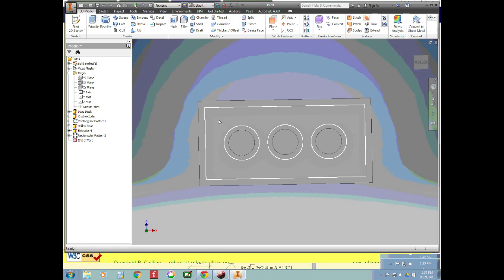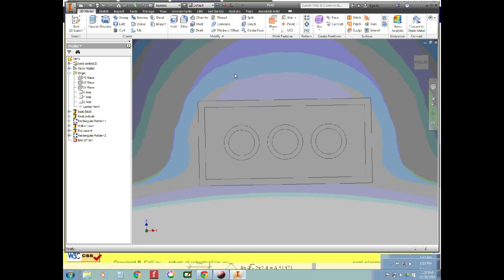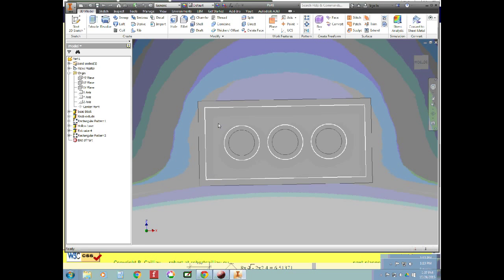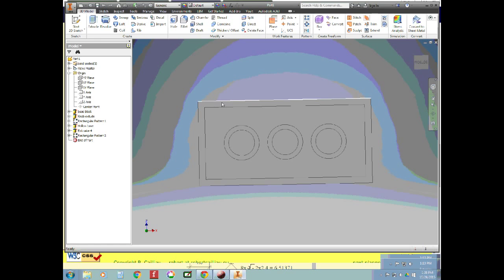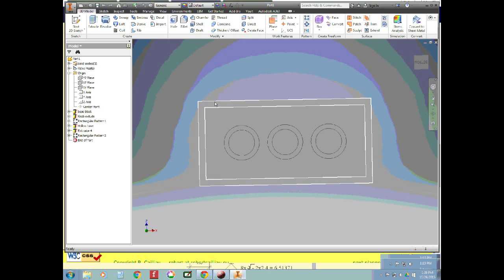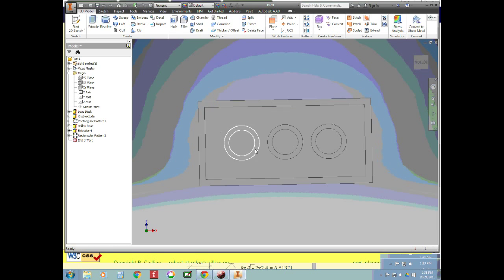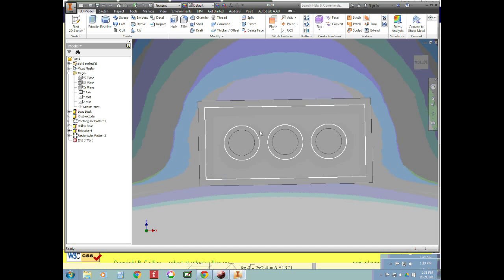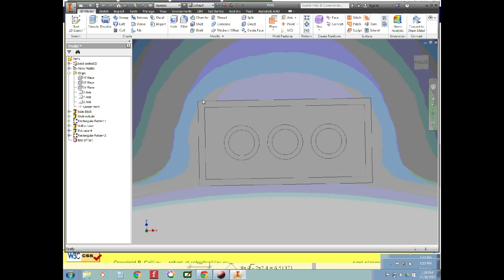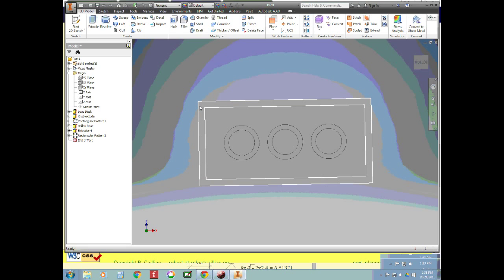We could draw it here and once again extrude it toward us. So I guess that doesn't really matter. You just need to be aware of where you've drawn it. And in this case, it's going to be a little bit easier if we draw it on this plane. We could have done the same thing with these. We could have drawn them in this plane and then extruded them back. I'm not sure that there's a huge difference as long as you're extruding them in the right direction.